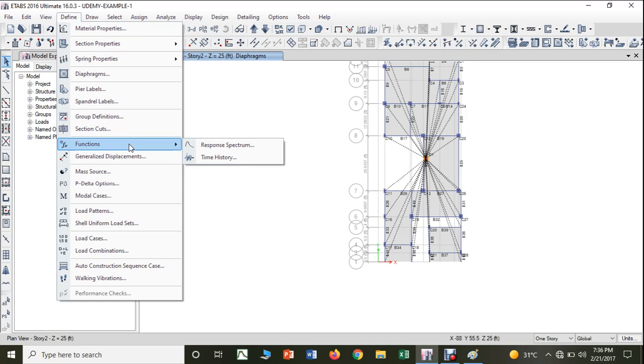If you design that particular structure for only one magnitude of the load, then if the magnitude of the load acting on the structure at any one particular point in that earthquake is higher than that, then your structure is going to collapse. So that's why when you are considering earthquake or wind, you have to design by considering the dynamic analysis, that means by varying the loads.